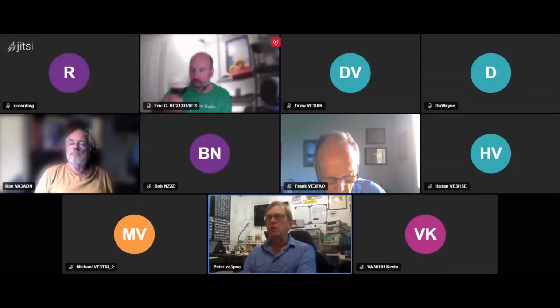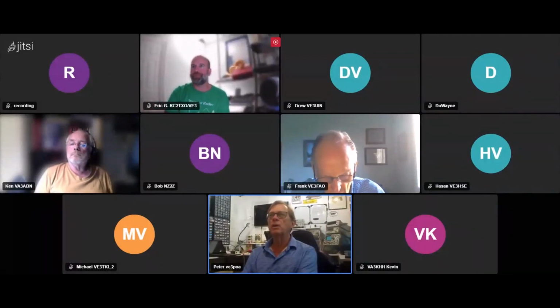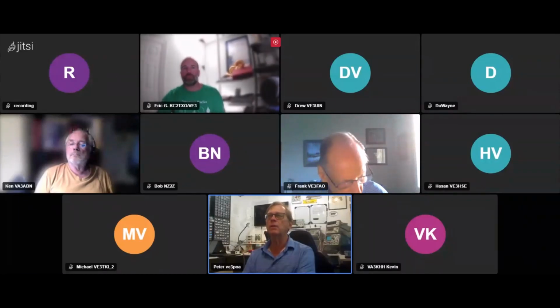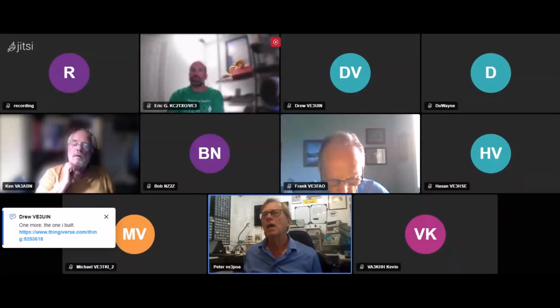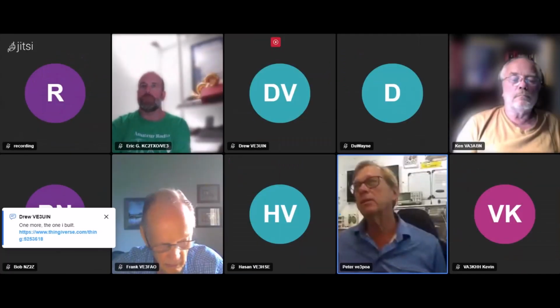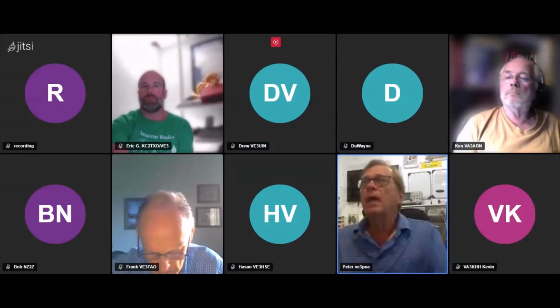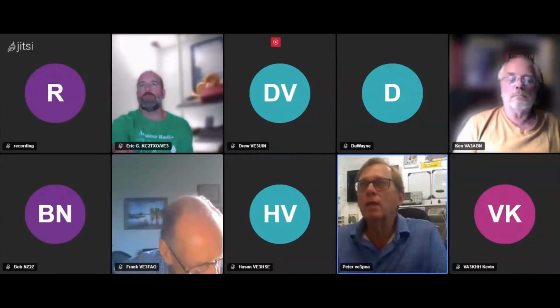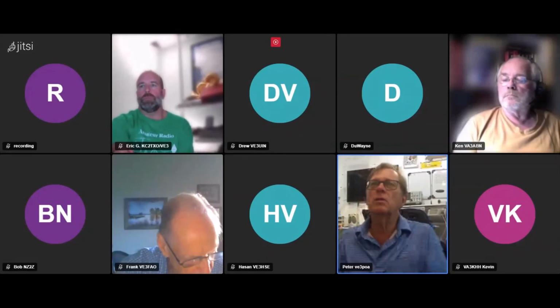So I did that. In the process, I also acquired an LTspice model for the 612. On my proof of concept board, I get a little bit of gain out of the first mixer. On Phoenix, I don't get a gain; I get a fairly substantial loss. I think I alluded to that at the last meeting. So I got a Spice model because it's time to start simulating this stuff. And sure enough, the Spice model does show a gain, and it comes pretty close to matching the gain that I experienced on the proof of concept board.